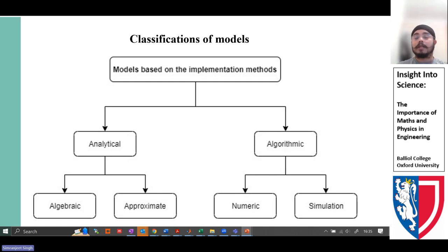So for example, they can simply draw in the code itself the geometry that you would like, depending on the width, depending on the height. Then once the geometry is drawn, the next equation would run. The next equation would talk about what is the density of air that you're considering, what is the area of cross section, and how much would be the velocity of the air.